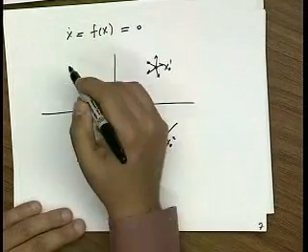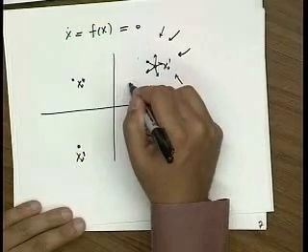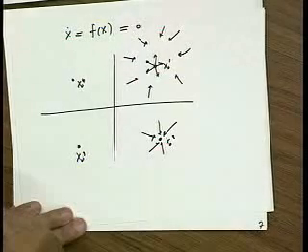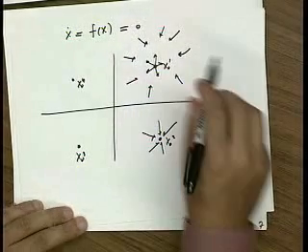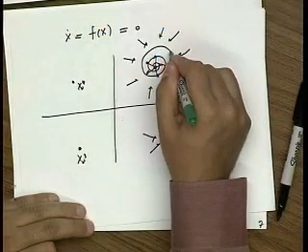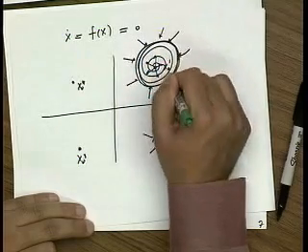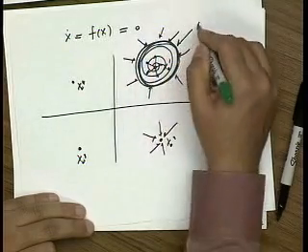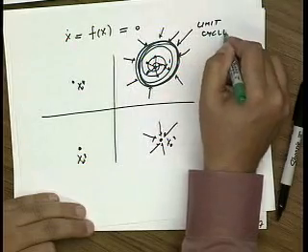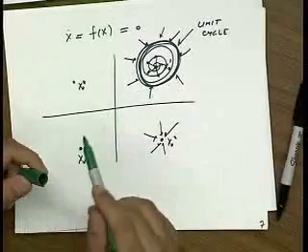And you can find systems that are unstable in such a way that they lead to limit cycles. In other words, any initial disturbance will get you out of this point, but if you get too big, there's a force that pushes you back. And this leads to what we call a limit cycle. Okay? And this is exactly what we want. We want equilibrium points that lead to limit cycles.